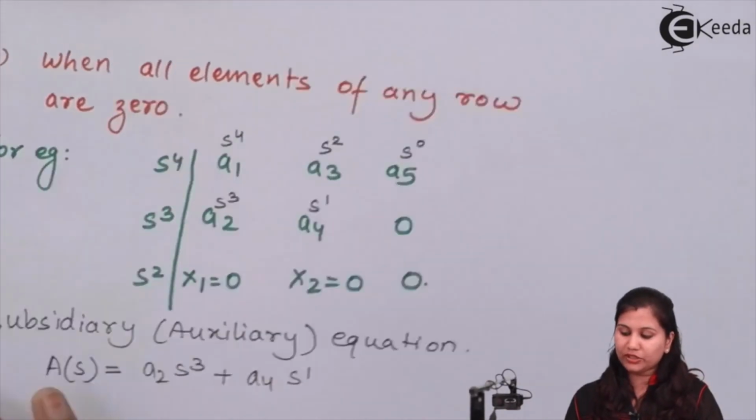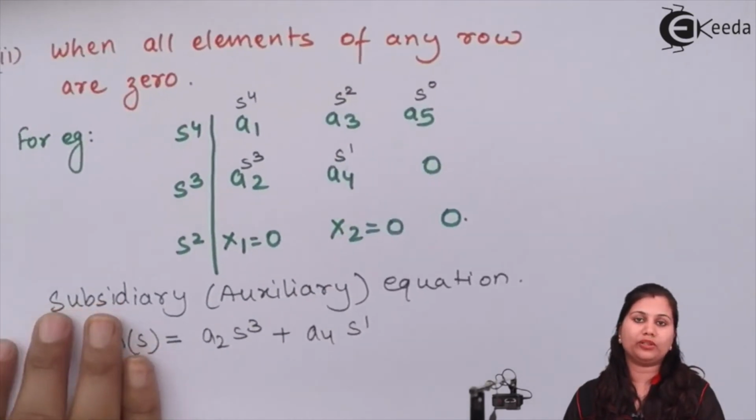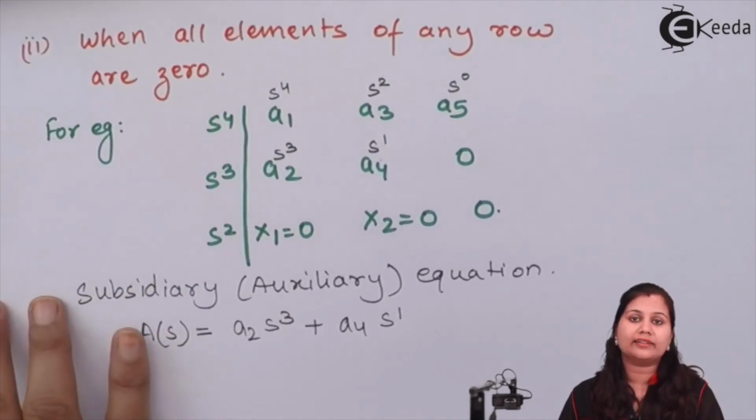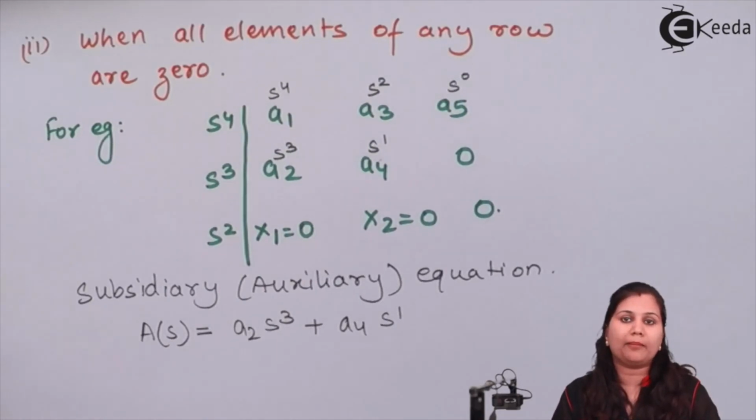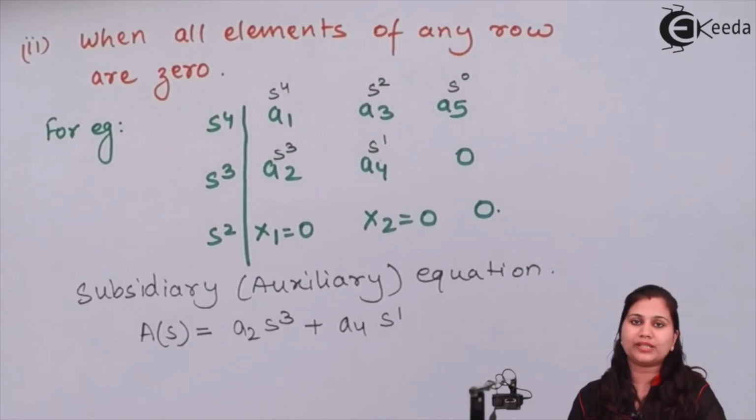So in this video we have studied the Routh stability criteria, how we can make a comment about the stability of a control system, whether it is stable or not stable, using the Routh Hurwitz criteria. You have to just use the characteristic equation, then form the Routh array, and then check the number of sign changes in the first column of the Routh array.